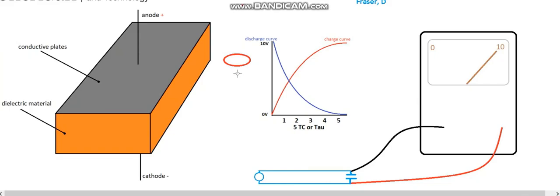you just very simply look like this. They just look like a cylinder. And you'll see these on motors. You'll see these on fan motors. You see them in capacitor banks, and there will be two terminals. There will be a terminal here, and there'll be a terminal here, maybe three terminals. It depends on the type of capacitor. You see them on air conditioning compressors, running caps and starting caps.